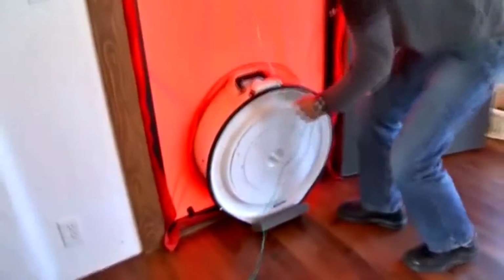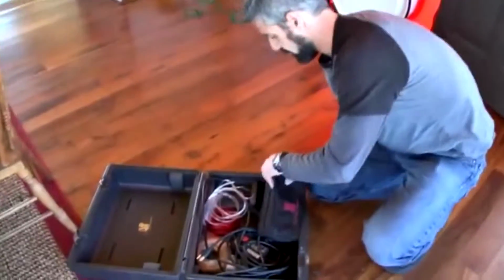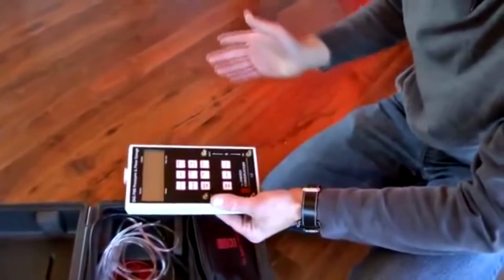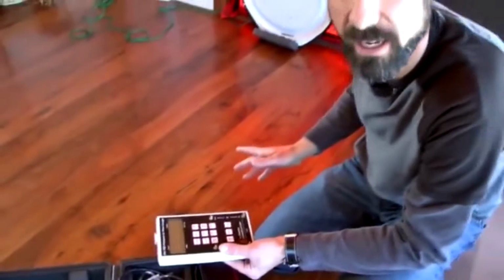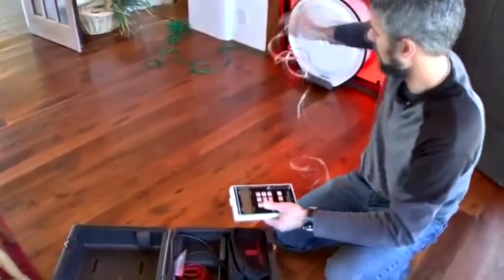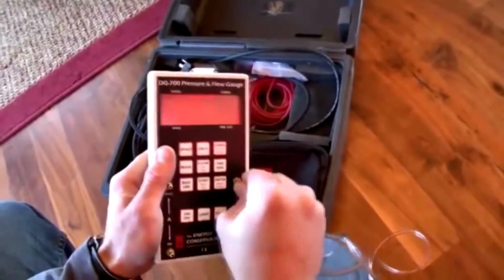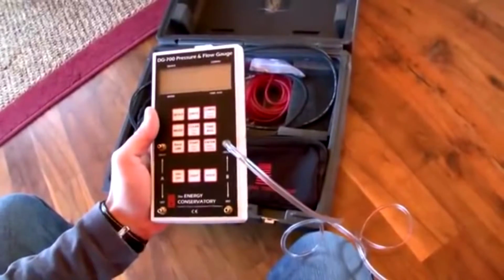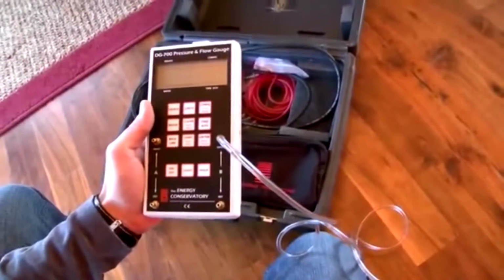We're ready to hook up some hoses here. So we're using a digital manometer here. This is the DG700. Again, a lot of different ones on the market. Some folks are using the analog gauges. Let's hook this up here. So this upper right port on ours is what we hook to the fan, and then that green hose that we saw earlier hooks to this lower left. So let's get it all set up.